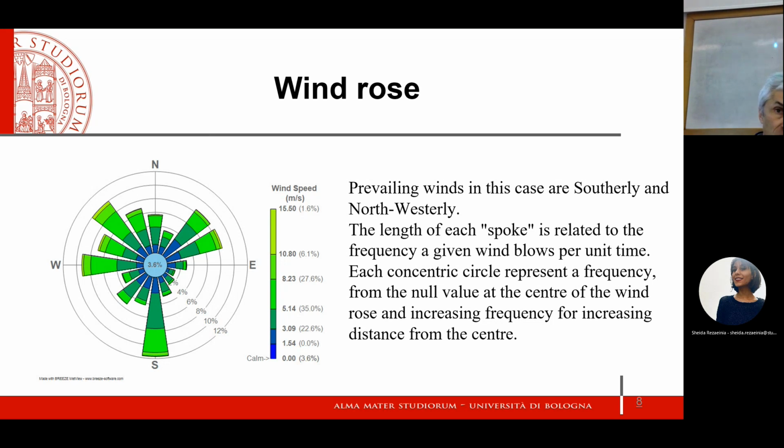So these percentages of time are frequencies. When I say 4% no wind, it means that I have a frequency of 4% of no wind. Frequency can be assimilated to probability. And therefore, this means that in each direction, through the windrose, I can estimate the probability distribution of the wind velocity, which is the information that I need.